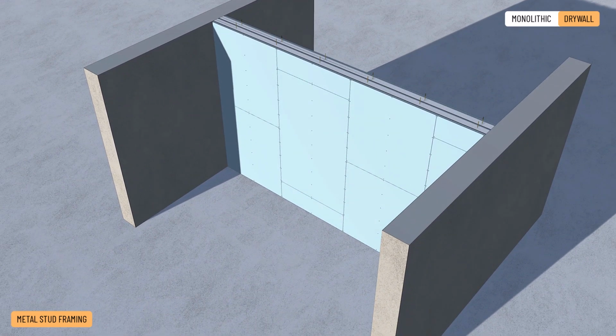Finally, the surface treatment is applied. The joints and bolt heads are filled with putty applied with a trowel, while reinforcing strips are placed along the joint. Then the perfect flat surface is achieved by sanding. If necessary, the puttying is carried out in several stages.